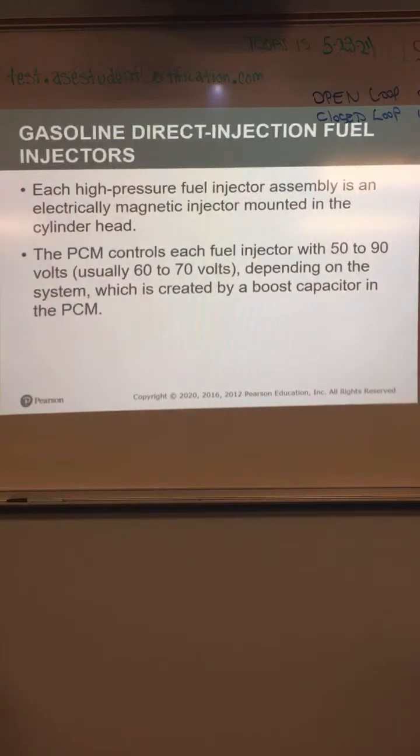I'm not exactly sure what your question was, but yes, high performance. Anytime you up the power, it's gonna need more fuel. Sometimes you can change the injector to a higher flow rate. That's what I was trying to ask. Gallons per hour, yeah. So what happens is the fuel injector itself flows more each time it opens. Okay. And you're able to manipulate that. Sure.